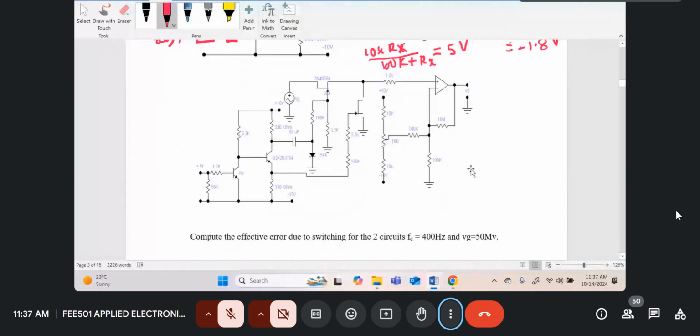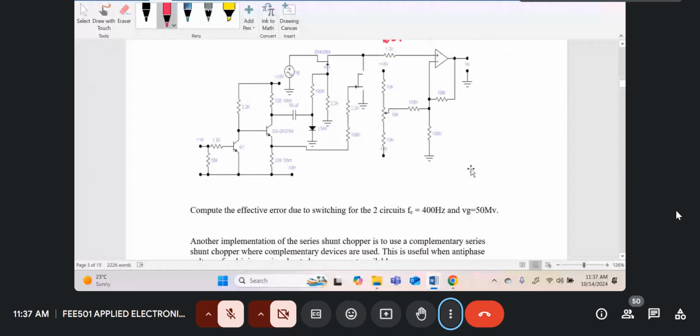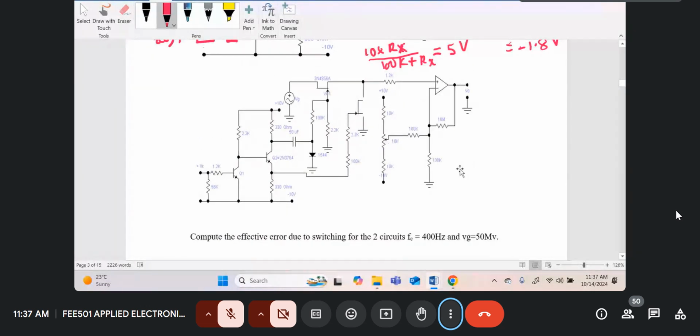Now there's a simpler application over here. The anti-phase circuit is just the same. You can try it out. This resistor is actually 22K, not 2.2K, just from the same example. This op-amp is just simulating an AC amp, because the gain of this circuit is approximately RF, 10 meg, divided by 100. Approximately, I said.